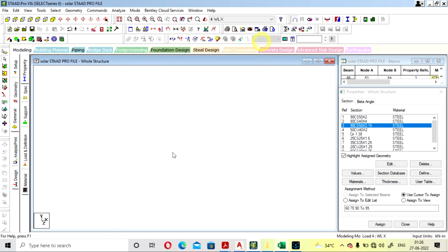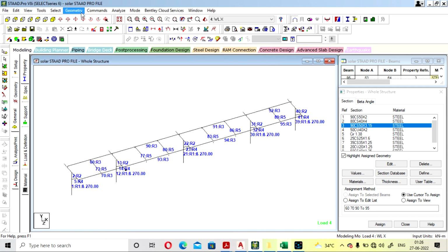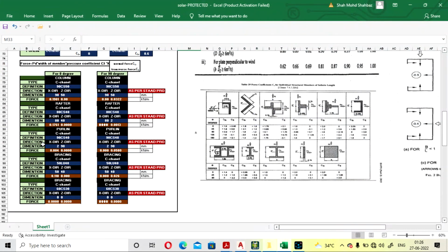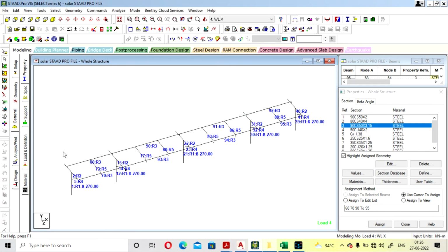So you can change your size according to your need, or if the structure is failing, you can also decrease the column distance if you want. Okay, by specification or fail, still it is failing, you have to increase the size again. Once you increase the width, the load coming will decrease. Okay, the forces that are calculated will decrease. So this will be a purlin, and if you just increase the 100. So you can also do that if you want. So now I hope you understand how we design the solar structure.